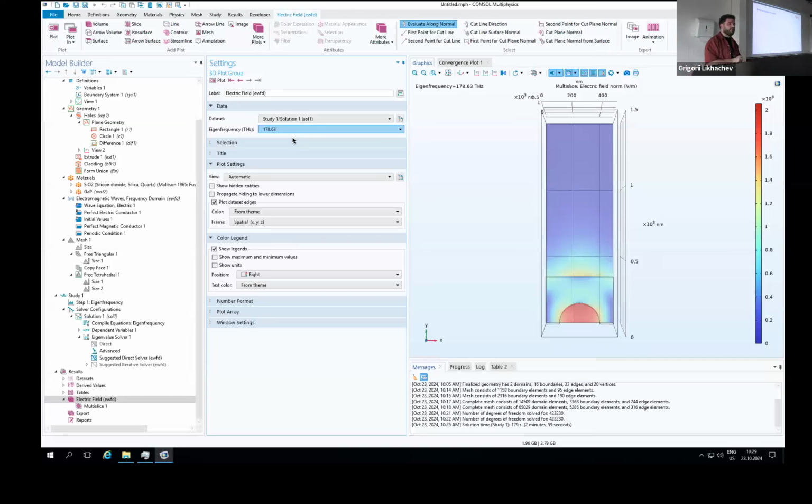For silicon nitride, usually people use the external accumulation. It's easier to fabricate, but they have bandgaps that are much smaller. Yeah, that depends on the material. For gallium phosphide, the holes need to be very small, like the radius is around 130 nanometers, something like that.